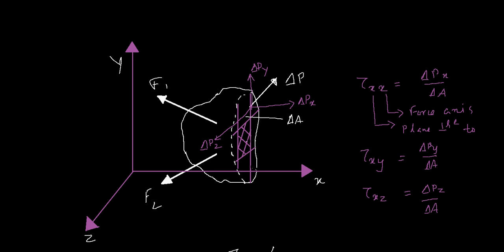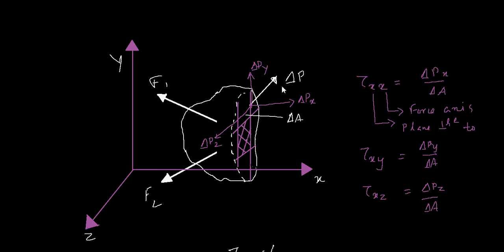So you have an applied force and an internal reaction. You resolve the reaction into three components, and then you find the stress corresponding to each of the force components. So you will have a normal force and a corresponding normal stress, and two shear forces or parallel forces corresponding to shear stresses. A normal stress is always denoted by the term sigma, and shear stresses are always denoted by the term tau.